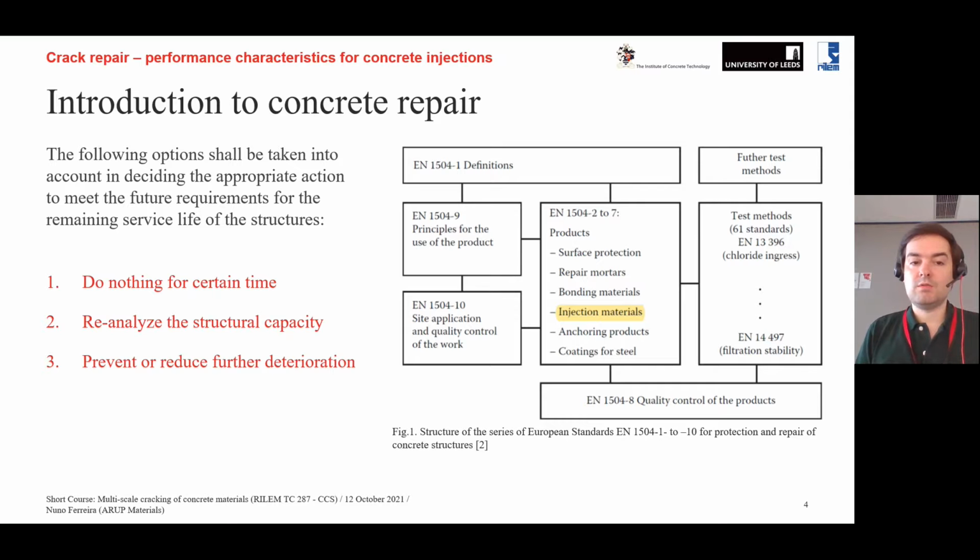The second step is to reanalyze structural capacity. Is the crack really interfering in the structural capacity? Are we getting a loss of load carrying capacity? And then the third one, I apologize, and perhaps also quite important from the point of view of waterproofing, is to prevent or reduce further deterioration. We all know that water brings aggressive chemicals and also accelerates corrosion. So it's also interesting to know whether or not we should stop the water ingress immediately.